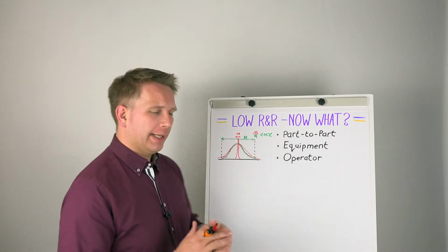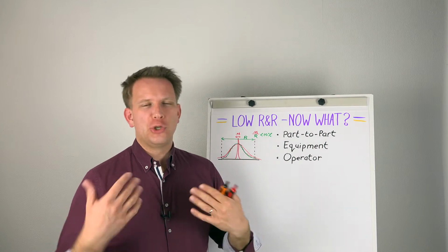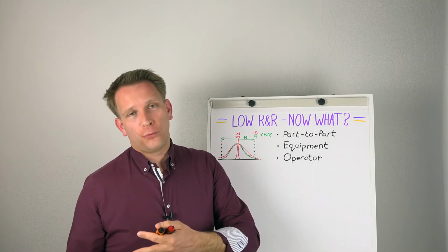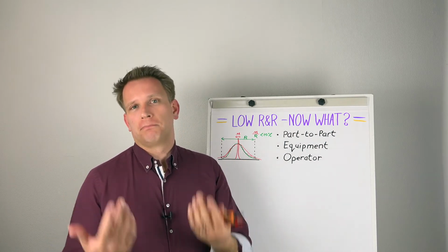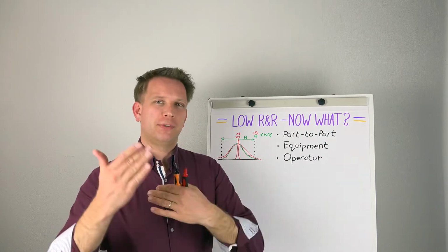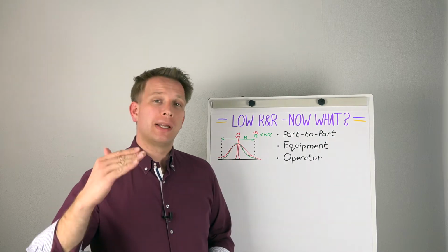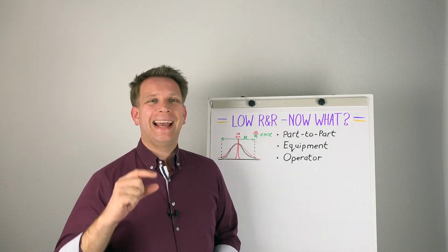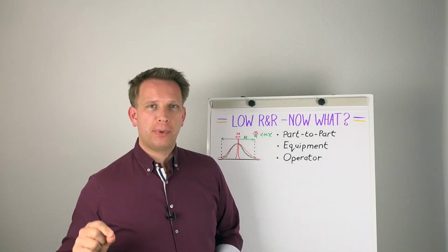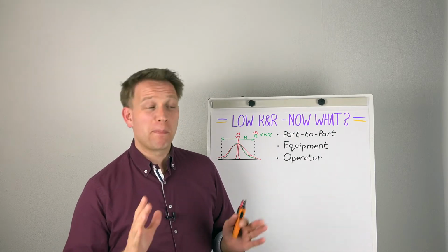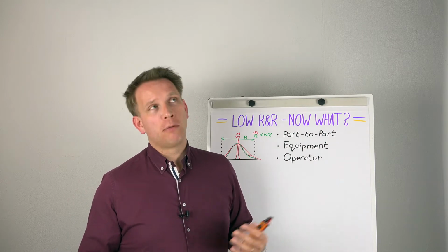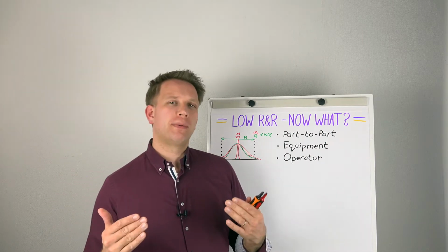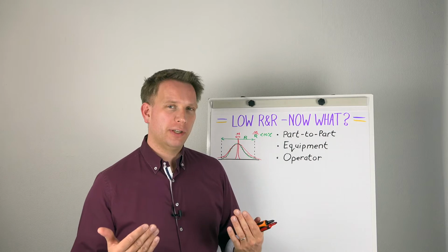We are calculating, and remember here that we usually make something like 3 to 5 different operators and do trials on, let's say 5 to 10, 10 would be good, different parts, and they test each of those parts also 3 times, maybe 5, but roughly 3 operators, 3 times 10 parts. That's a basis. That's sort of the minimum that you want when you're doing an R&R.